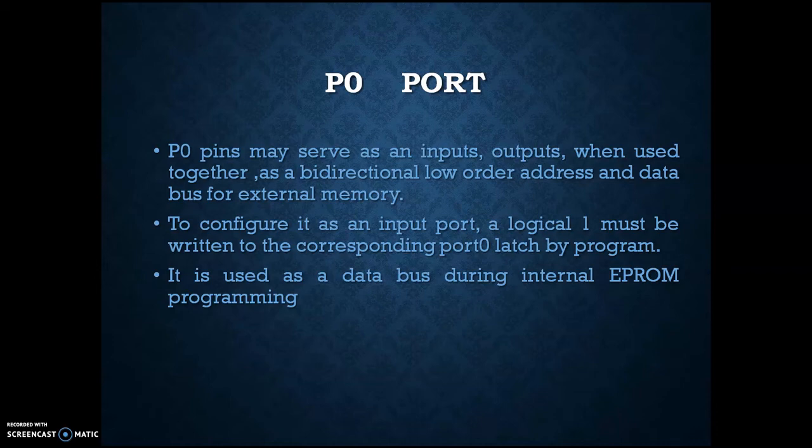So P0 is nothing but address data multiplex. When used together, it acts as a bidirectional lower order address and data bus for the external memory. To configure it as an input port, P0 must be connected to logic 1, that means high voltage, and it is used as a data bus during the internal EPROM programming. This is the characteristic of the P0 port.